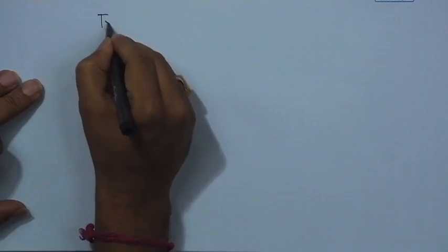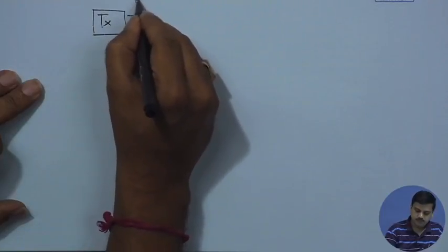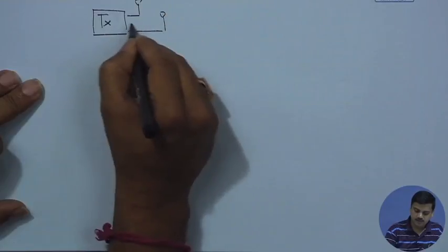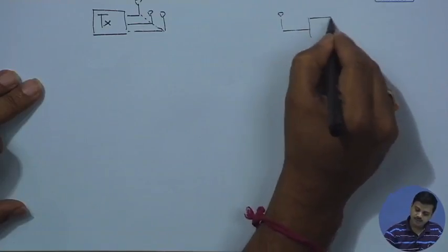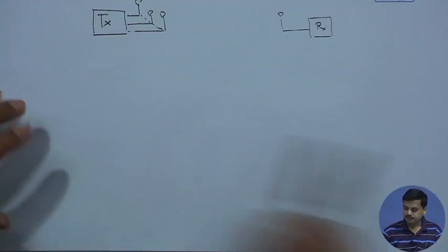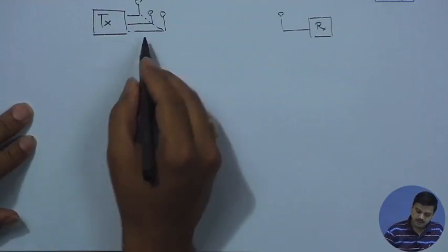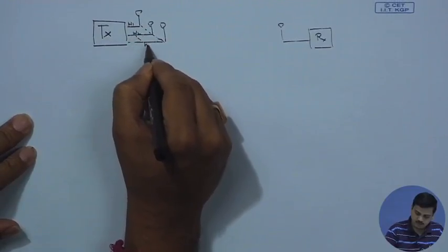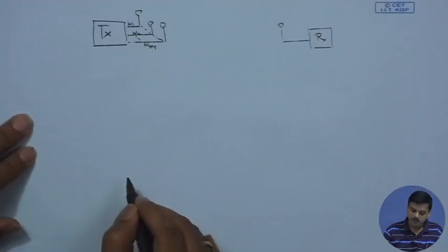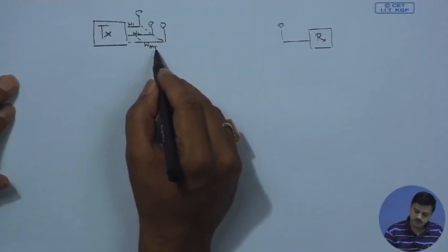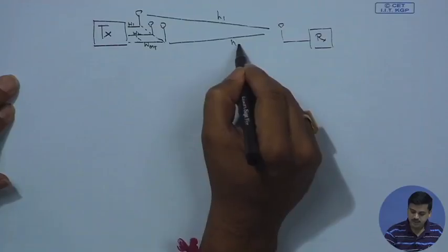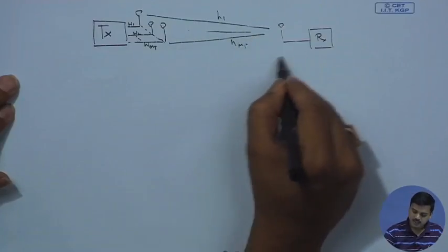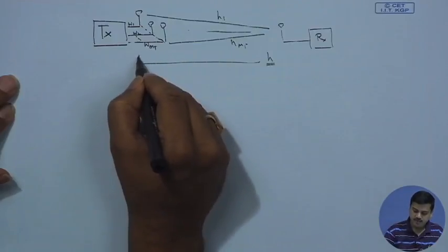Now, when the channel has to be known at the transmitter, we should remember that there is this transmitter with several antennas, and let's say the simple case when there is one receive antenna. This is the most simple case. In this case there was a W1, a W2 up to W_MT used at the transmitter. That means we had weight factors, and these weight factors were proportional to the channel gains. So if this particular link was H1 and the last one was H_MT, we had all these links. So this entire channel vector H had to be fed back to the transmitter.